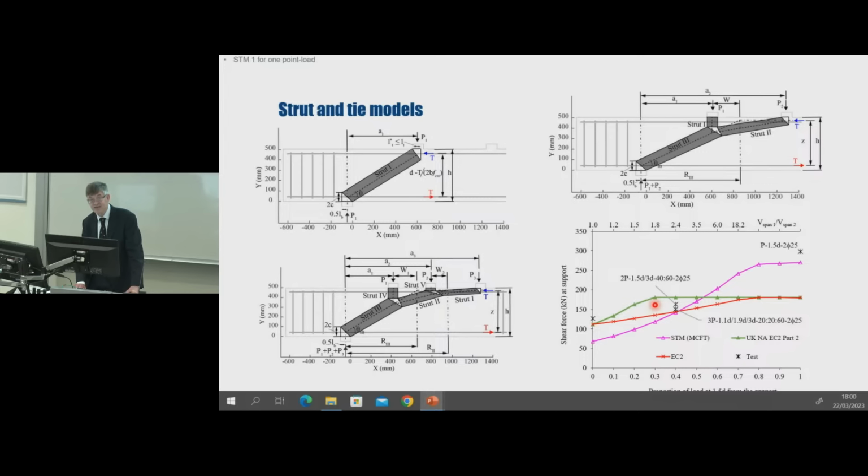So in this case study, I hope that I've convinced you, first of all, that laboratory tests are important for establishing the behavior of reinforced concrete members, particularly in shear. Detailed measurements of crack kinematics give us interesting insights into shear resisting mechanisms. And then finally, and perhaps most importantly, hopefully I've shown you that mechanically based design models are preferable to purely empirical ones.